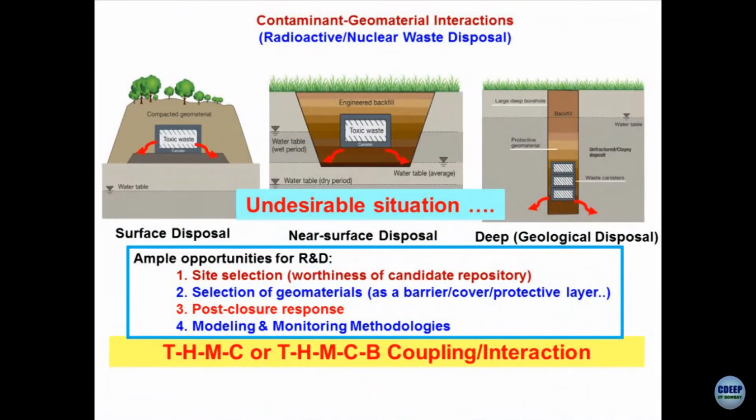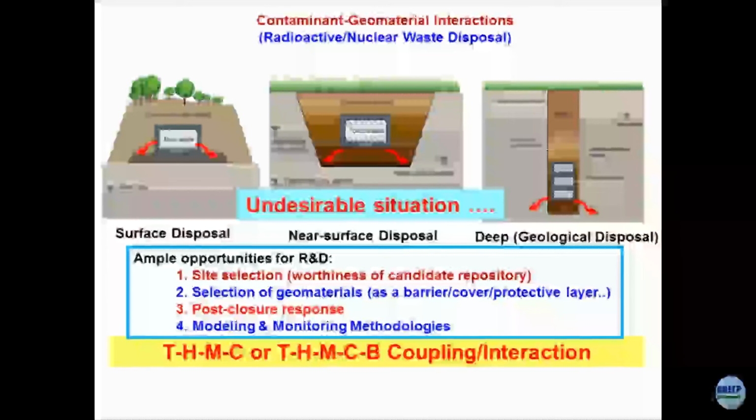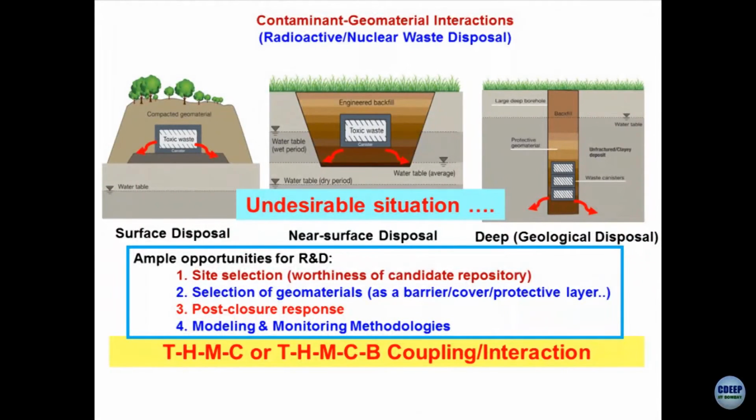They should be protecting this unit against the rains. Compacting them itself is a big challenge because the buried units are there inside and these buried units are quite active. So, you can't just say I am compacting it. The properties required: nothing should come out of it in any liquid phase or gaseous phase. The water table should not fluctuate so much that everything becomes wet. Forget about the instability, which you can take care of. Vegetation should be done because plants ultimately provide a cover.